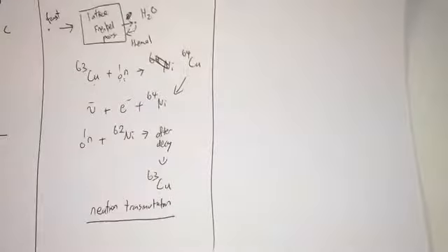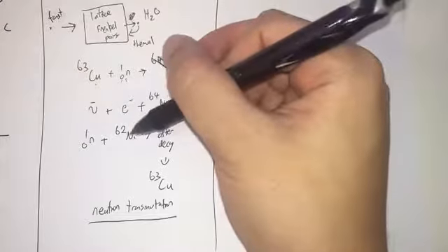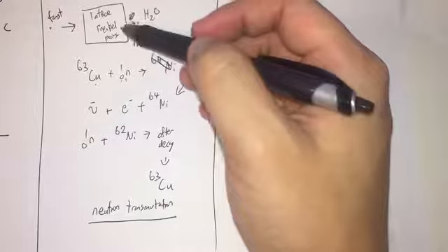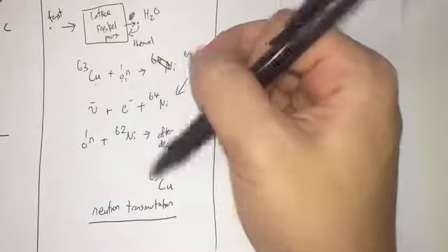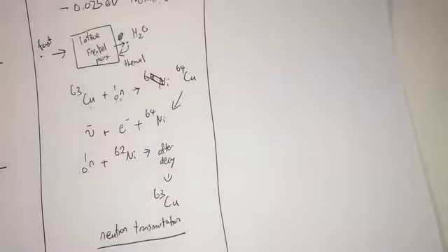So this is a very common effect inside the steels of a reactor pressure vessel. Even if there is zero copper inside the metal lattice, you can actually form copper because of thermal neutrons being absorbed. You can refer to some of the links I'm placing, just for your information.